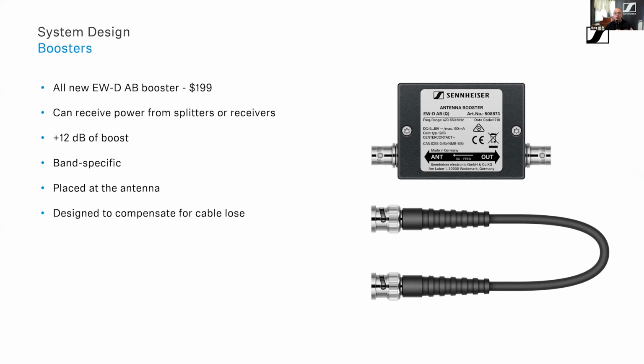So the first thing you want to do is see if you can get a lower loss cable. And you always want to be calculating out your cables. Depending on how long your cable is going to be, there are a ton of resources online or from the cable manufacturers that tell you, hey, if I'm at a specific frequency with a specific length, this cable will give me a certain amount of loss.